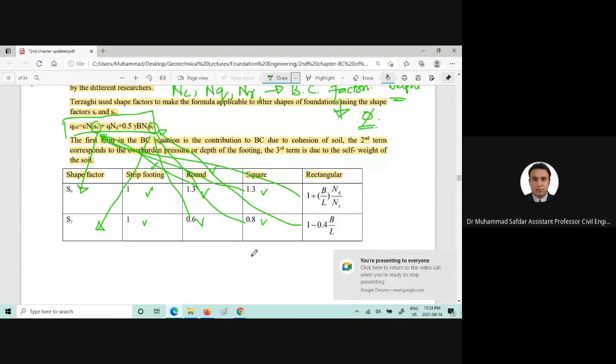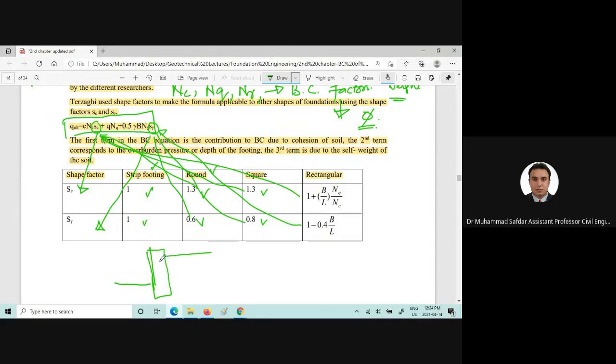Yes, this is the same thing, you know. So if there is a retaining wall here, and this is the upstream side, and this is the downstream side, and then if that wall is moving towards the backfill material, there is a pressure which will be applied because the wall tries to move into the soil, and this soil will exert a pressure which will be the passive pressure.